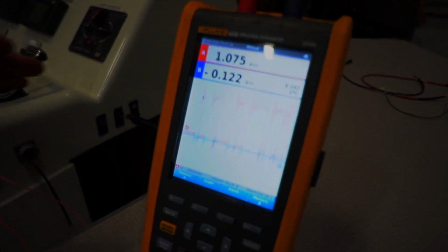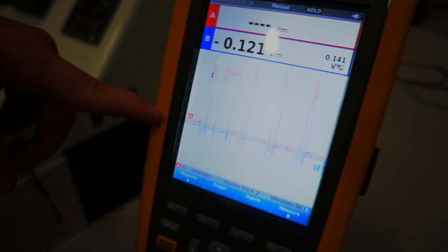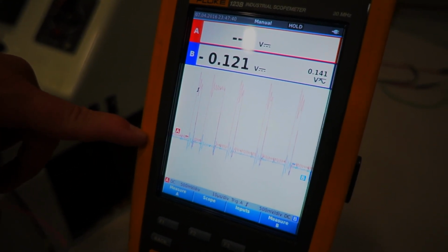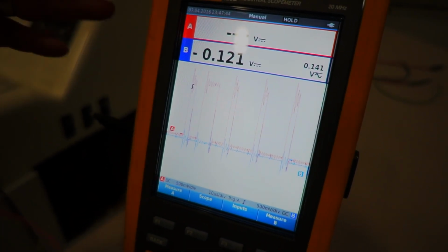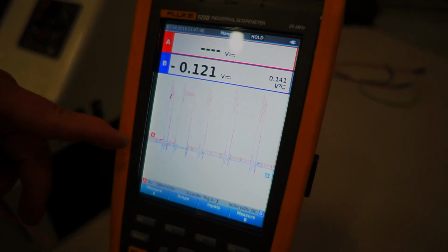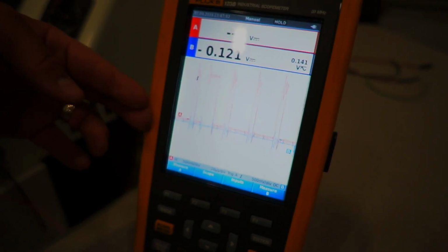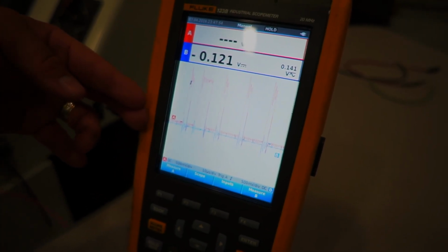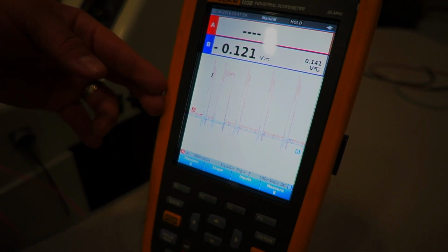Now our signal looks a lot different here. We can see, if we pause this here, our CAN negative is the blue. It's the one that's grounded, right? And then our CAN positive still looks pretty similar to what it did. So if you think about this, what's happening? The differential voltage between the two, when they're down here on the low end, is still near 0. So that would be that bit 1 that we were talking about.